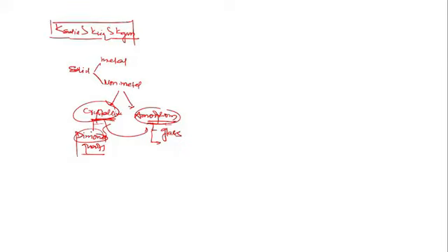watt per meter per Kelvin. What does it mean if the thermal conductivity of the diamond is 2200? I told you thermal conductivity is equal to the rate of heat transfer when the temperature gradient is unity and area is unity, yes or no? So it means if the thermal conductivity of the diamond is 2200, the rate of heat transfer through diamond is 2200 if the temperature gradient is maintained as unity and the area for heat transfer is unity.